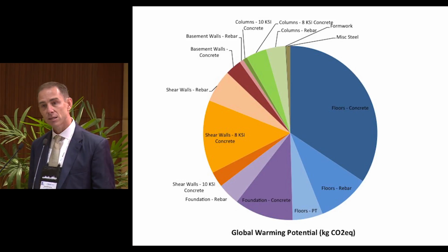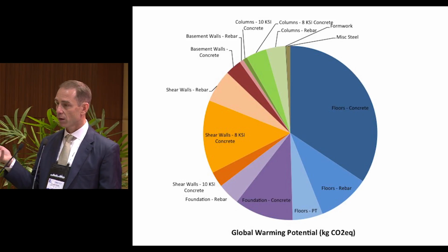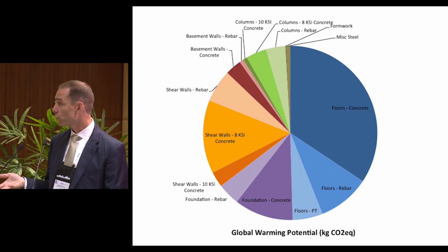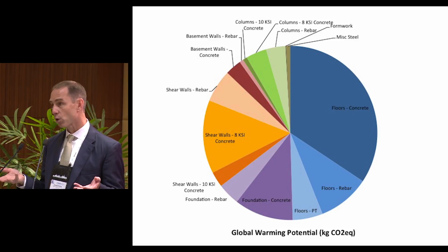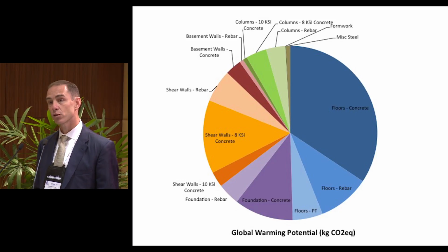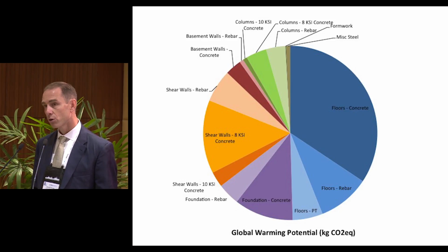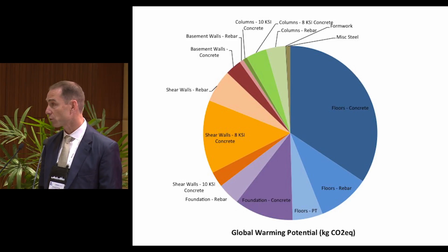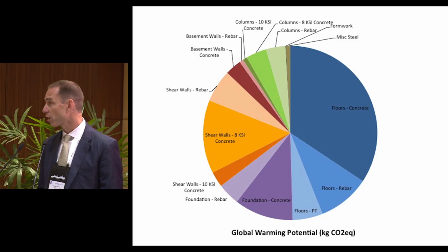Now, the punchline in Seattle, and I'll use that rebar as an example: Nucor is one supplier that has a very aggressive process, and their environmental footprint is very low. Their competitors in town selling a commodity material at the same price, most of it is shipped in and made elsewhere in the country in locations that are coal-fired generation with a much higher carbon footprint. Simply by asking the question, you can greatly vary the carbon footprint of your building without even changing the design. And so that's one of my biggest reasons to say you really have to do it as a two-part process, and it really has to become part of our buying decision.